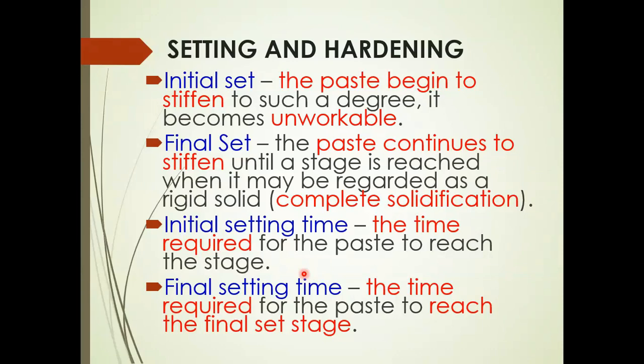In setting and hardening, we also have the initial set, which is when the paste begins to stiffen to such a degree that it becomes unworkable. The final set is when the paste continues to stiffen until it may be regarded as a rigid solid. So the initial setting time is the time required for the paste to reach the initial set, and the final setting time is the time required for the paste to reach the final set.